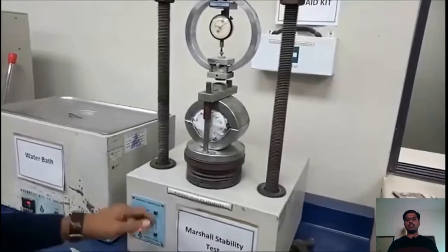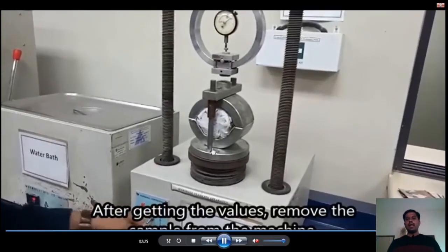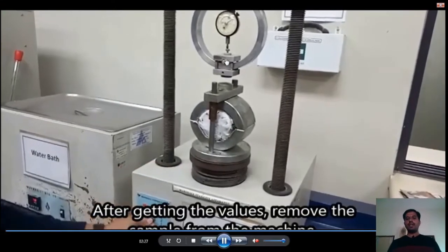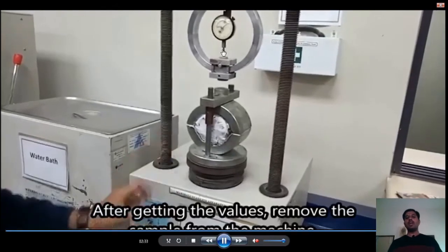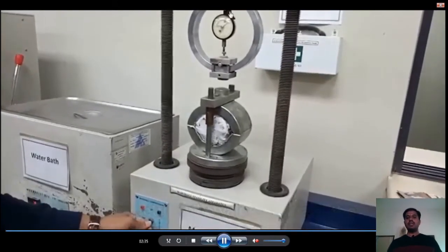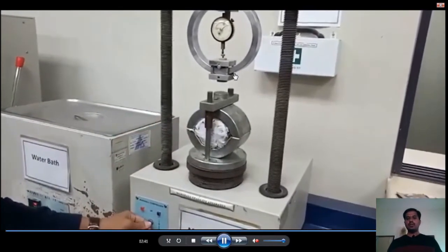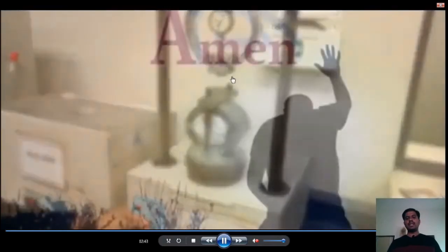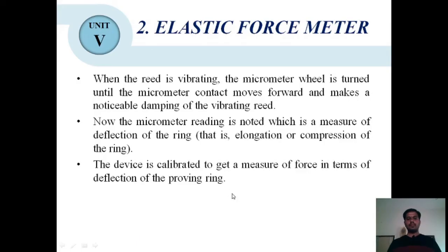That means the concrete has broken up. The moment at which this dial gauge stops indicating values, that will be the amount of force generated on the proving ring. At that moment, the amount of force will be noted. As soon as this dial gauge stops giving the deflections, it will directly give us the amount of force exerted on the proving ring.